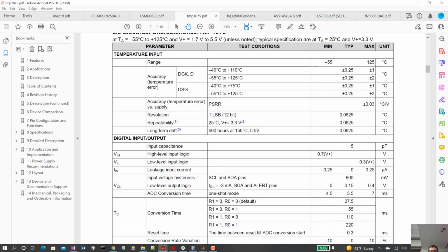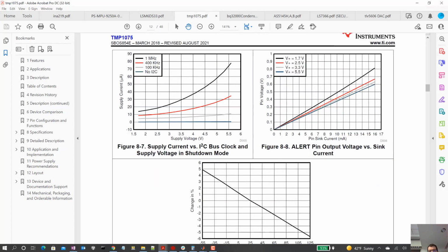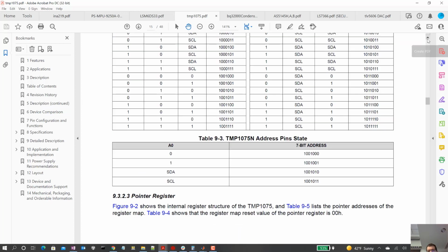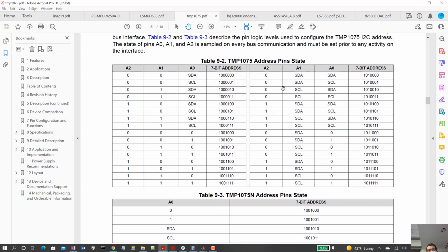Okay, so then by setting those address pins to certain values, and this is a little confusing. Oh, here it is, yeah, good. So you have your address 0, address 1, address 2. And so you can wire address 0 to the SDA line. That's kind of interesting. I wonder how that all works. But in other words, it figures out its address on power up. And so it's not always monitoring the SDA line when that thing is going high, low, high, low. It's not changing.